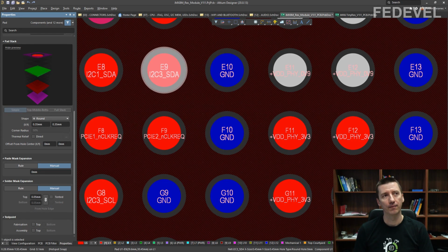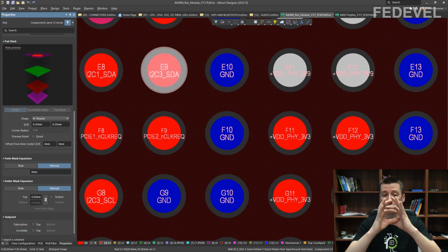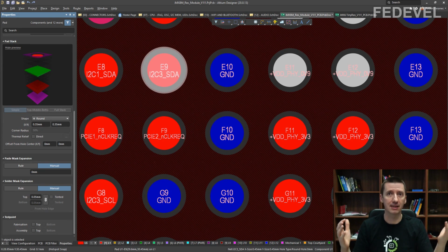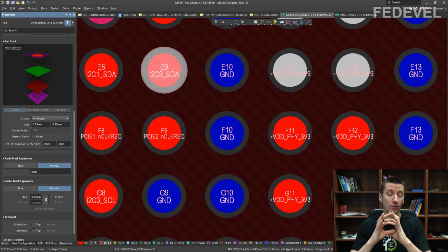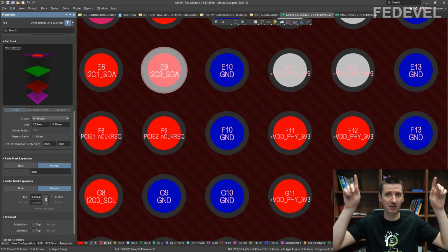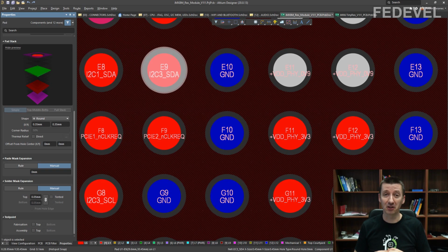Still, this means that when you are designing small PCBs like computer on module, small PCBs, the price of these PCBs is maybe somewhere between $10 to $20, and this kind of increase, 30 to 60%, is not so much for so small a PCB. But if you would like to use these vias in pad in large PCBs, then it can cost you quite a lot of money.